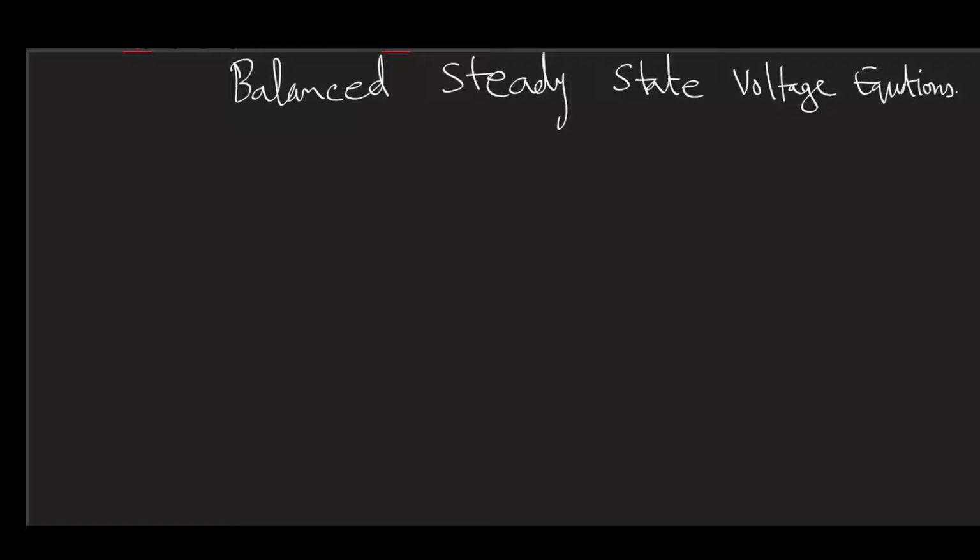The steady state current and voltage will be the same. Also don't get confused that in case of fault we can't have steady state. Although these two are a bit contradictory, like fault means something very unsteady, something undesirable happening, after the fault takes place, if you allow the system sufficient time without taking any other action to disconnect the fault, then the system reaches its new steady state with that fault.